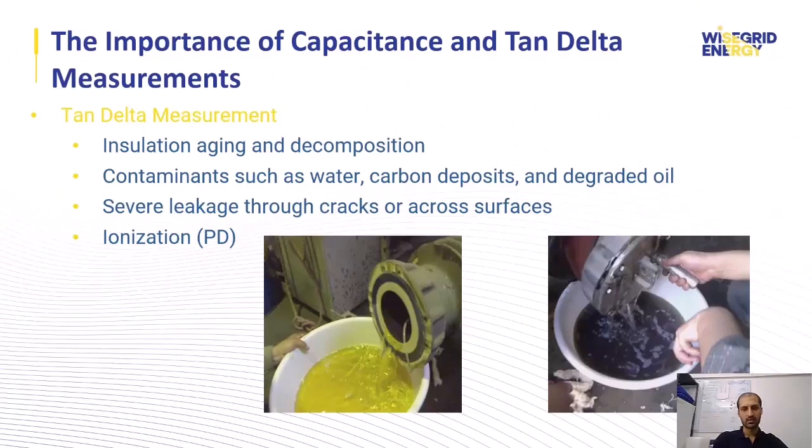When the paper inside the insulation overheats, it carbonizes, producing carbon particles that dissolve in the oil. This leads to increased leakage current and maybe sometimes partial discharge in the insulation. These localized breakdowns and heats inside the materials increase losses and further degradation of the insulation.